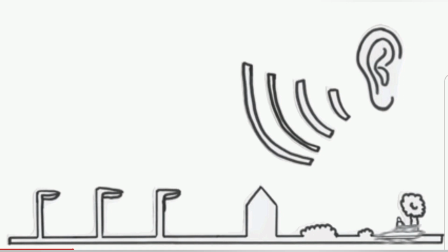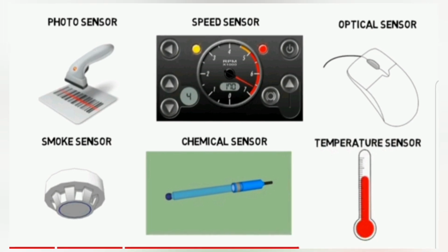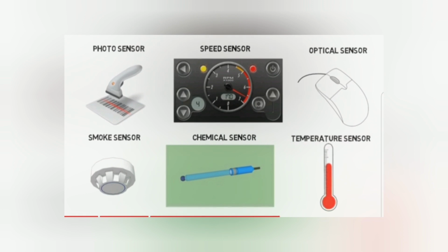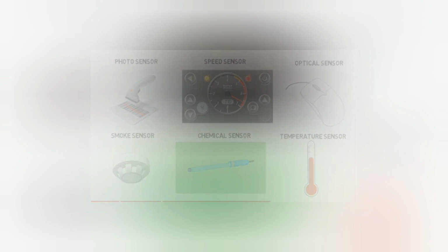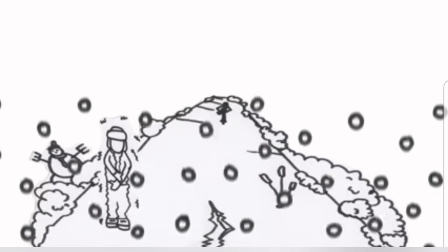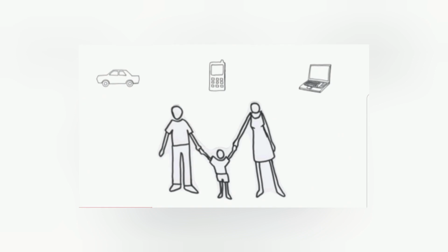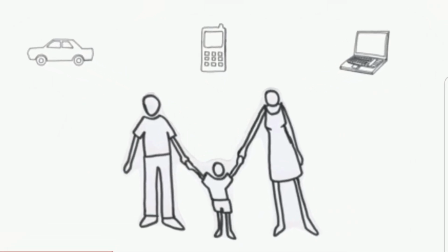All right, now that we have talked about sensors and the physical properties that they can sense, let's discuss how they are used in industry. Almost every sensor used in process control will be connected to a transmitter because the sensor's output needs to be conditioned or amplified. Here's an example. We already talked about a thermocouple and the voltage output created when it is heated.